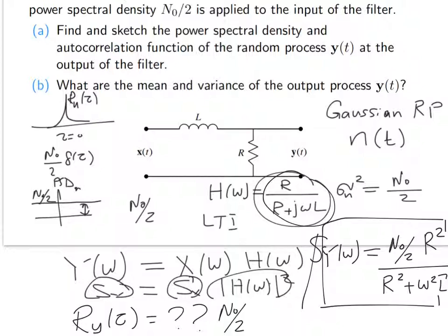So you can say that this is N R, right? Take one R outside, and then you end up with R divided by R squared plus omega squared L squared. But this won't work. You want the omega to be without a coefficient. So you have to divide everything by L squared. Okay? So it will become R over L, and this one will be another R over L divided by R squared over L squared plus omega squared. Right? And then this is the frequency domain one.